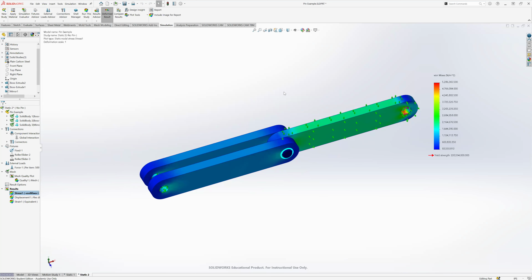The shear stress tau is equal to V over A, V being the shear force. V in this case would be 500 newtons divided by 2, because it's shearing at two different places. You can do it that way, or you can literally double the area. That's another way of doing it. Either way, you get a very quick calculation, and you may not have to literally run a simulation to find that out.